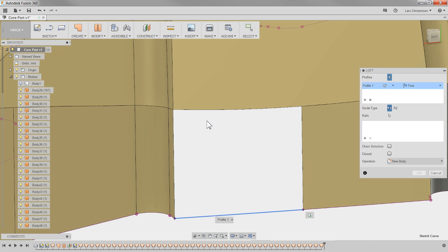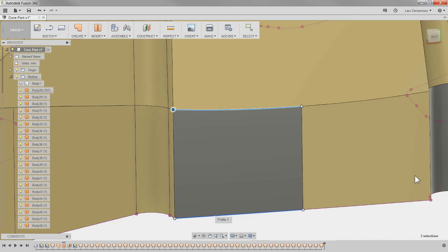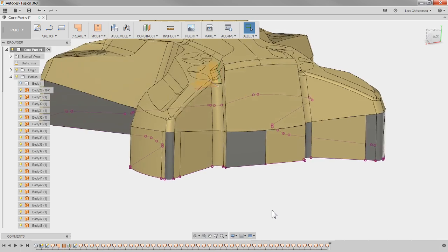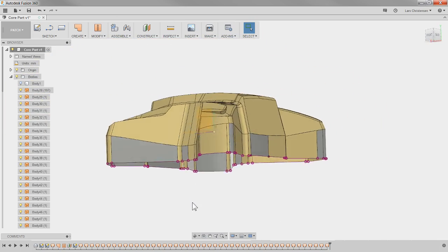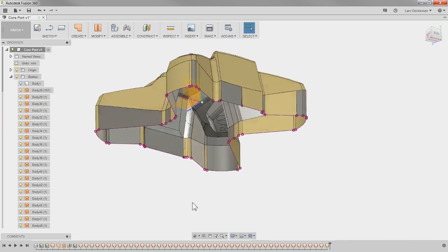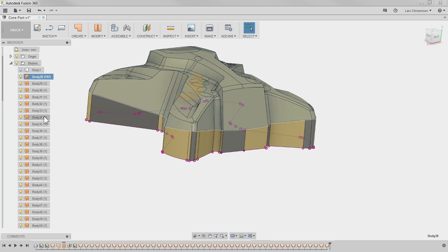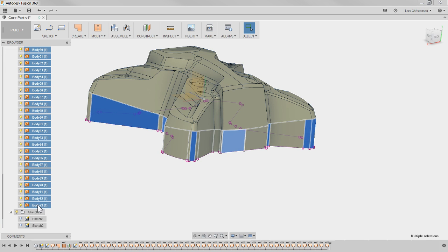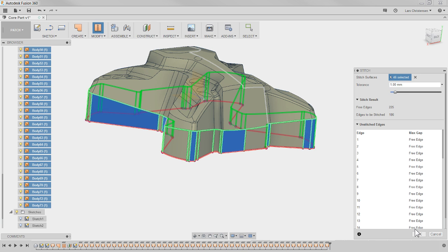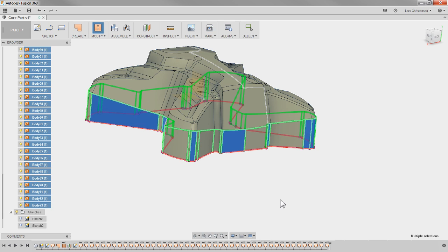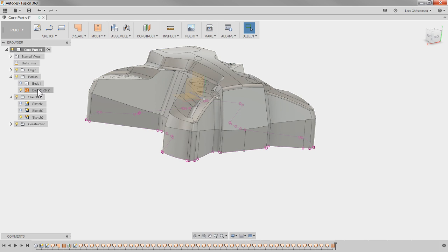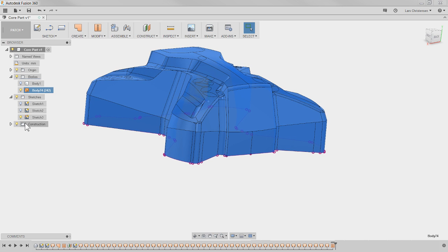Last one. Okay, folks, we made it all the way around. All right, so now you can see that I created that, and of course, again, I'm ending up with all these different bodies that were just created. And again, I'm just going to do what I did before. Hold down the shift command, select the top and the bottom, then you can select them all between, and I can now stitch them together here. Now we've got 240 surfaces here. Now we're just about there.